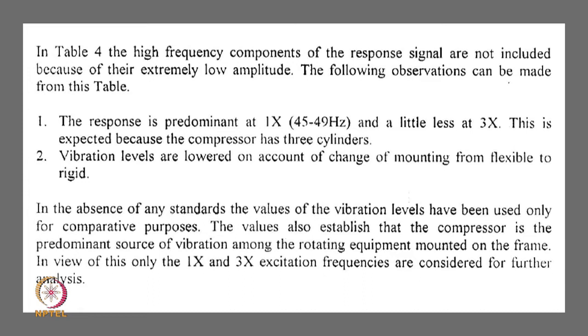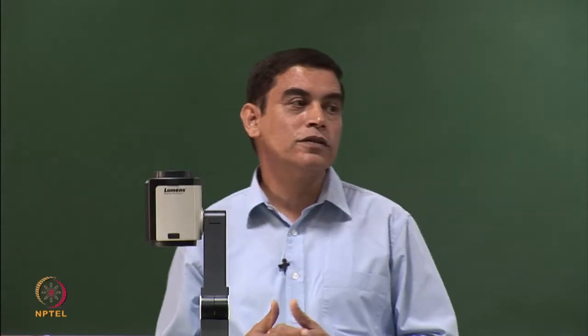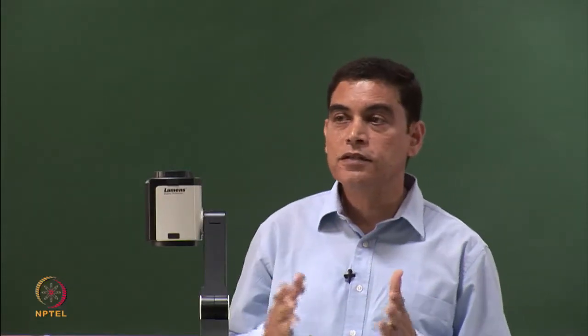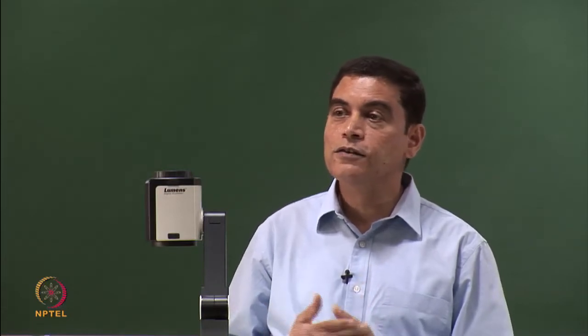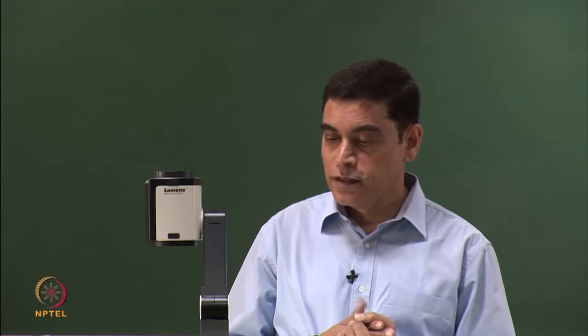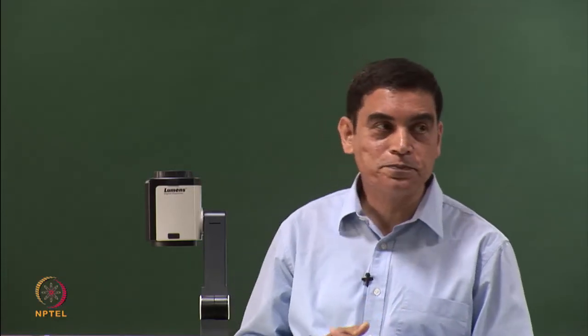Now why is it that 3x is becoming important? So the compressor that we were using had 3 cylinders. So the third cylinder means there would be a certain vibration peak at 3x of the frequency. This again was something which was a learning.